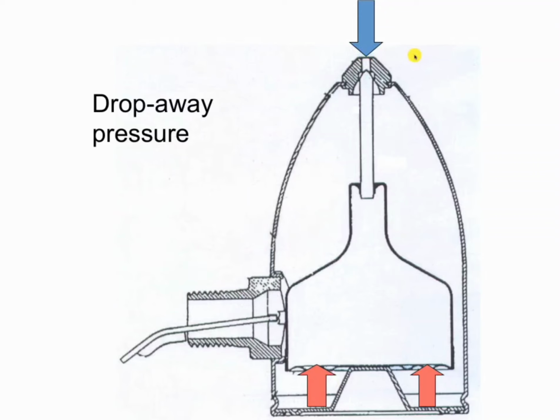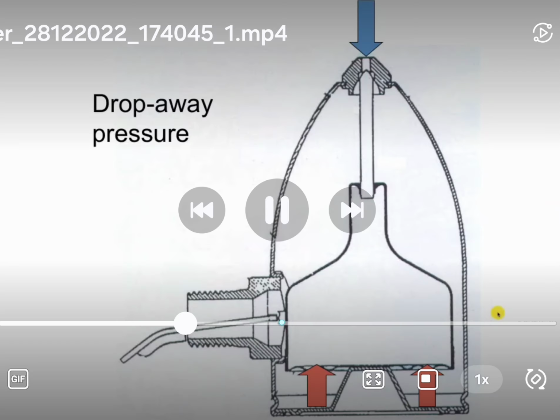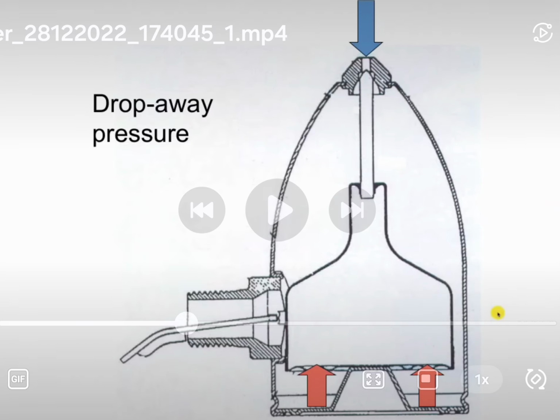"That was the challenge that we had with that New York City housing project that was taking Con Edison steam, which came in at a constant pressure and never dropped. The constant pressure just held the vents closed. And before the air is out, the radiator's full of air. The steam's trying to get in. The radiator won't get hot because the air can't get out. So we want to lower the pressure." Let me just pause it there.